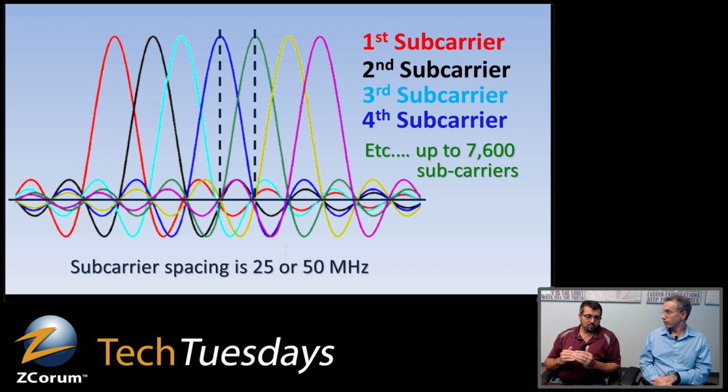But those different profiles have different modulation orders. And what happens is you define where in your OFDM channel which subcarriers, each little slice, can do those higher order modulations, right? A device can lock on, and that's where the next code word pointer comes in. That's when the CMTS says, hey, you expect those are where your code words are going to be, and it's at this profile level because of your capability.